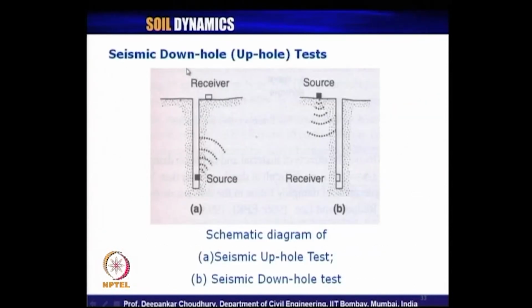Another type of common test is the seismic downhole test or seismic uphole test. So, what is the uphole test? Look at figure A. If in that borehole you put the source of vibration inside the borehole and keep your receiver on the ground surface, that is called the uphole test.